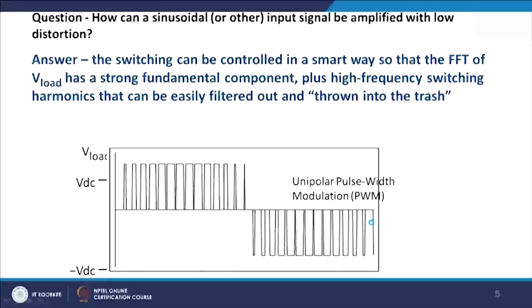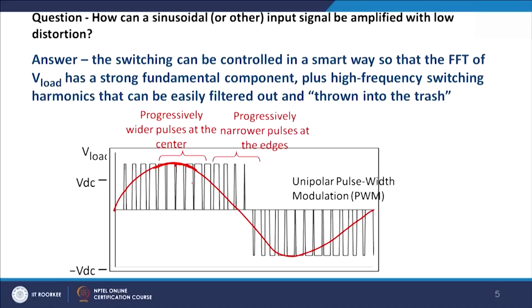So these are basically the PWM signals, where the volt-area will match. It is not that we are applying a sine, but the sinusoidal volt-area and this PWM volt-area will match each other. We will come to this later; this is called unipolar PWM, and this is one of the advantages. You can see that since the area in the central portion is more, it will be more square at the center, and it will have narrow fringes at the beginning and end of the cycle.